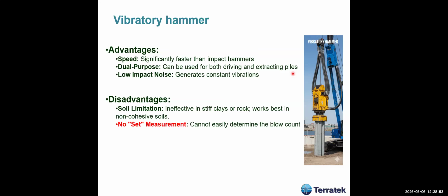I have used this in the past. Usually, in that project I've shown you from Rolls-Royce, we used two hammers: a vibratory hammer to drive the pile, and another hydraulic hammer that came just after it to measure the set. This was very important.